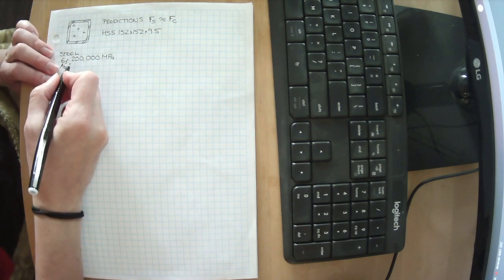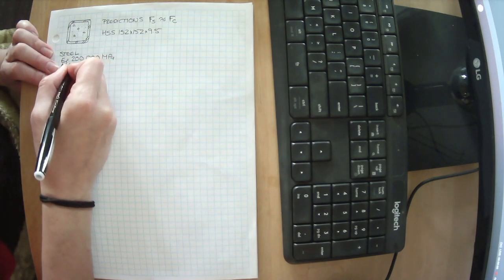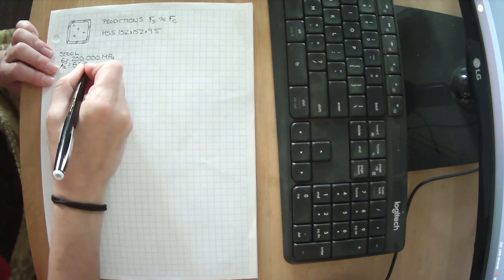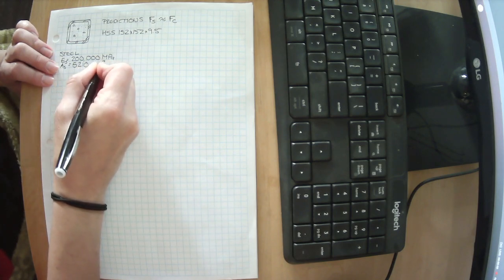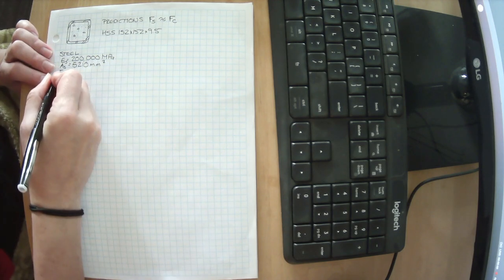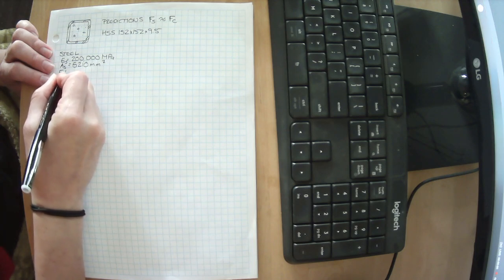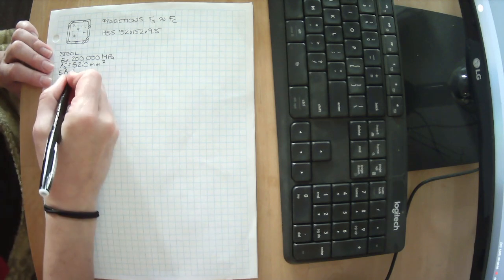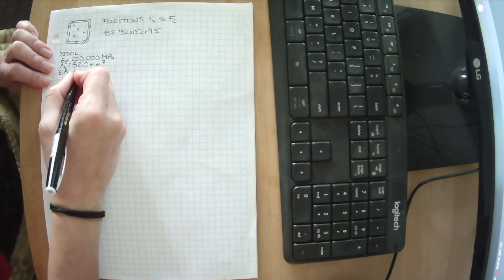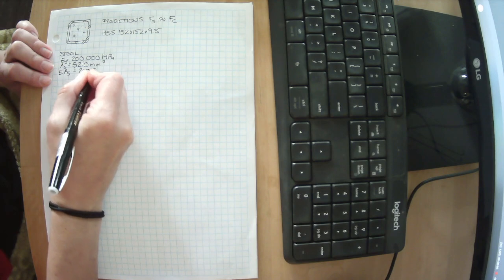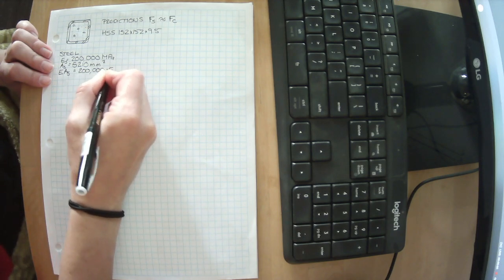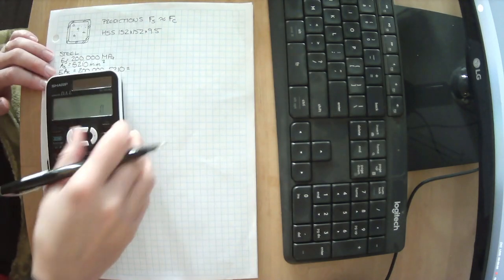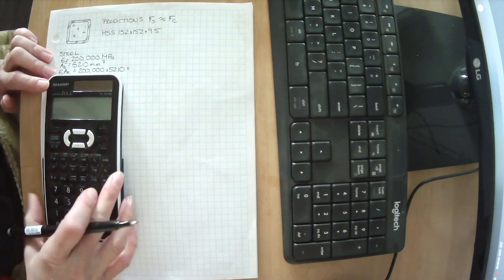So the area of the steel, if I go look that up, I will see that the area of that particular member is 5,210 millimeters squared. And I know that this EA_s, the E of the steel and the area of the steel, is going to be kind of important. So why don't I just calculate that right now? I've got my 200,000 times my 5,210. Looks like it's going to be a big number.